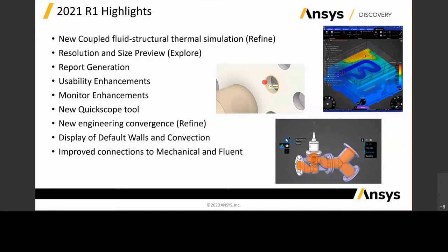It will take us a little while to port all of SpaceClaim across to the new style of interface, but the new style of interface you'll see is the same ribbon tab that you're familiar with in SpaceClaim. Where the rest of the graphical user interface was panels, like the structure tree was in a panel, you'll now see the structure tree being inside the graphics scene. And then some of the controls, as you can maybe see in that top right-hand screen grab, you've got heads-up displays giving you access to the pull command and move command and views and stuff like that.